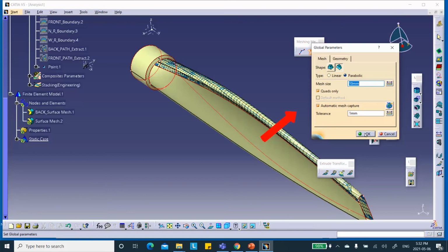What I should have done was to join these surfaces and then make sure that when you mesh, the direction of the draping direction and the join are opposite to each other. That's one thing I forgot to do, and we have to go and fix this.